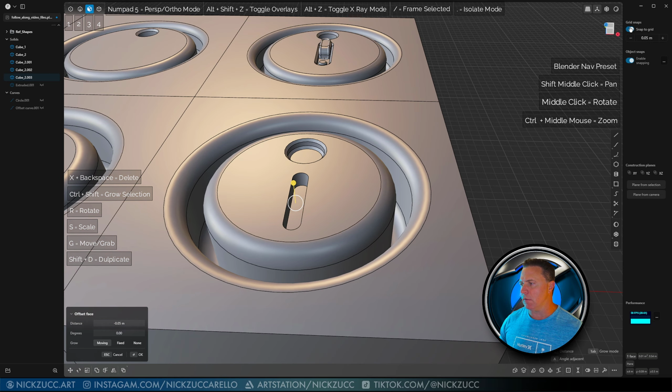The next thing I'm going to do is mirror this, but you can see my world origin is way over there. So if I want to mirror, I can select this curve, hit Alt X, and that's going to give me the ability to mirror across. And normally this is really easy. I would just select that and it would mirror it across the X-axis. That's not what I want because that's way over there. So what can we do about that?